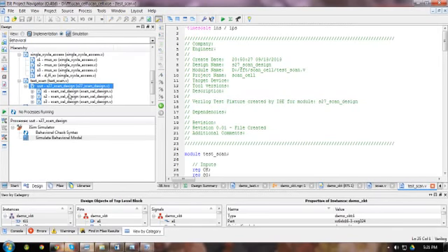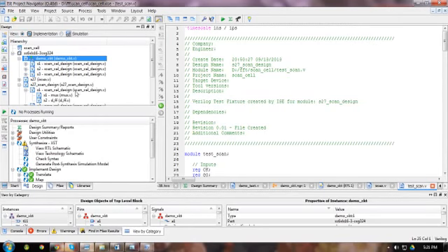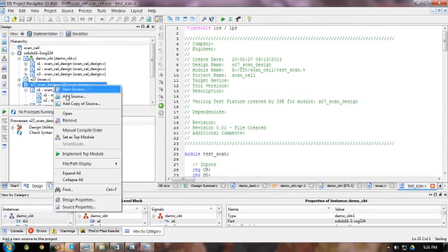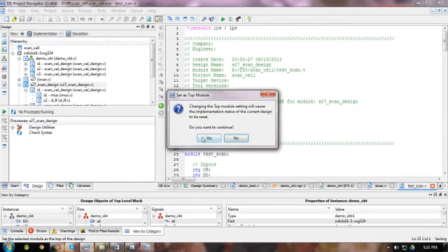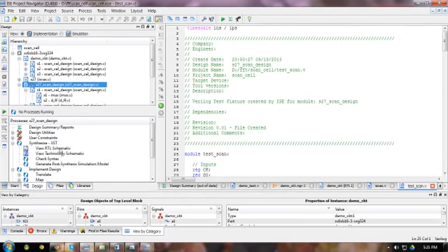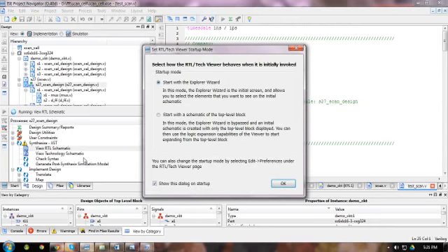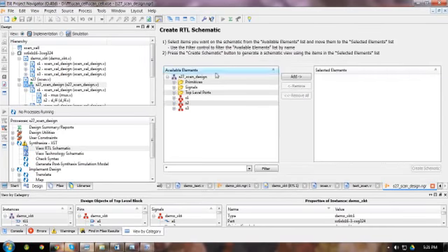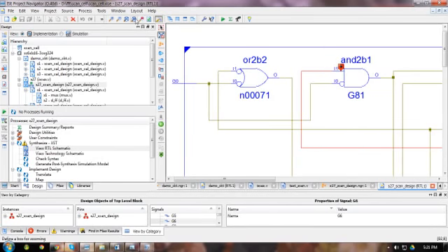If you are still interested in experimenting with this, you can take the benchmark circuits like the ISCAS S27 which I used here. Let us go to the RTL of a more complex design, which are also called benchmark circuits. And let's run the RTL. My idea is to just show you how big a sequential circuit can be, and how to convert that design to a scan cell design.